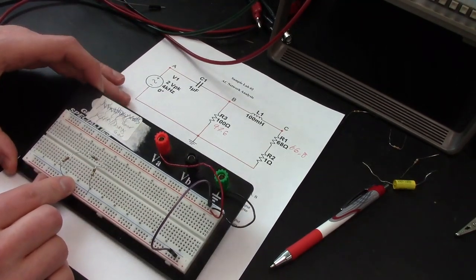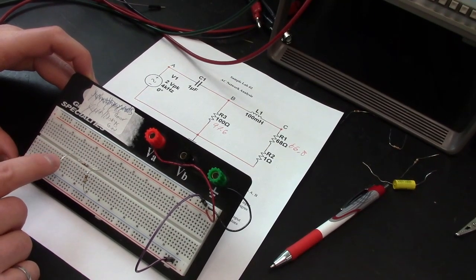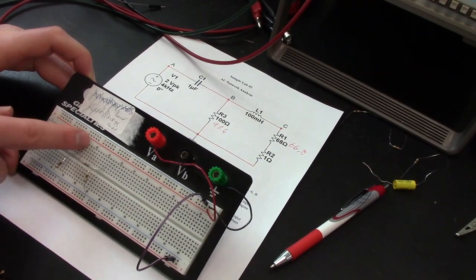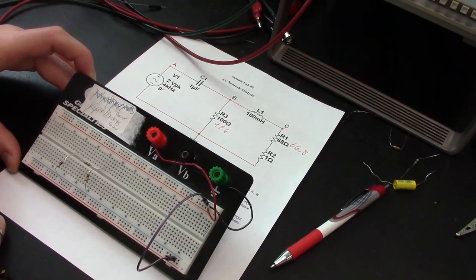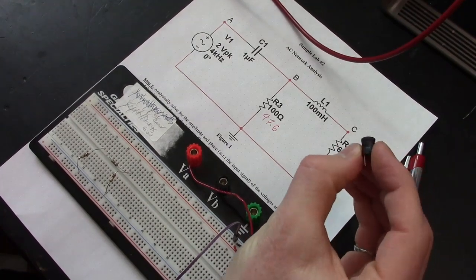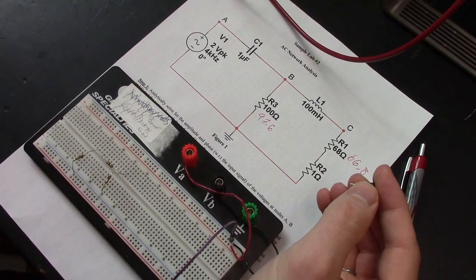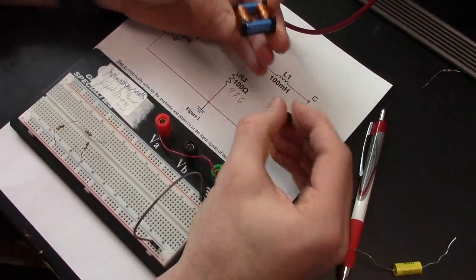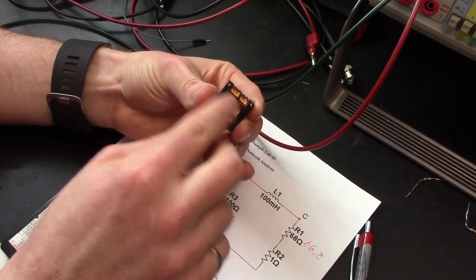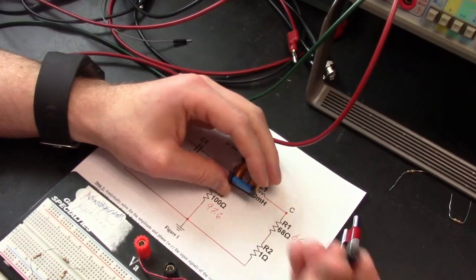So the other components that we need are an inductor to bridge between these two top connections, the top of the 68 and the top of the 100, and we'll need a 1 microfarad capacitor to go from this junction up to the high voltage of our supply. Alright, so for the inductor, the inductor looks something like this. This is our 100 millihenry inductor. You might also have one that looks like this style. So in this one, you would connect this terminal to this terminal is 100 millihenry, and it actually has two on the one little piece there. This one is just two terminals, so it's 100 millihenry between them.